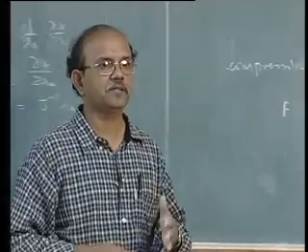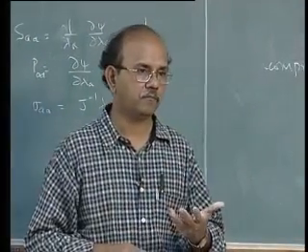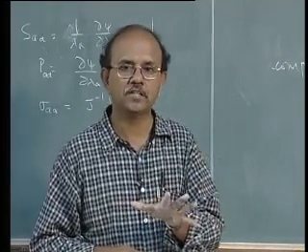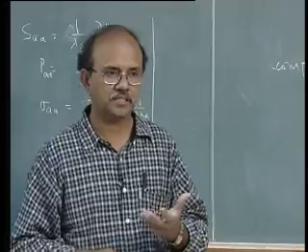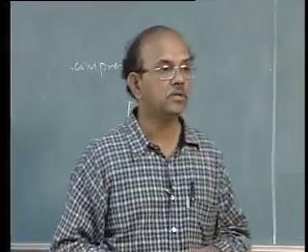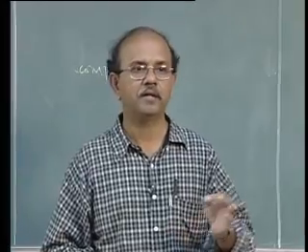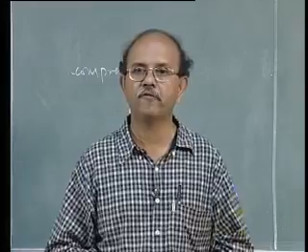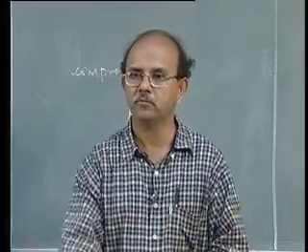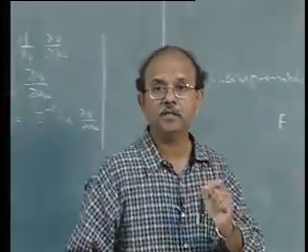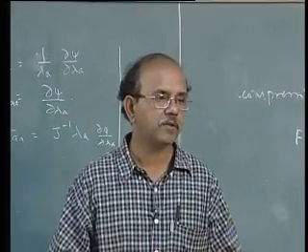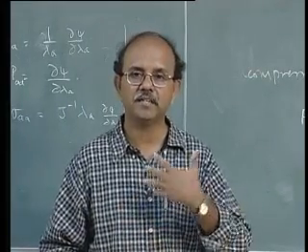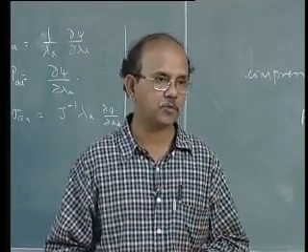Though we say that they are nearly incompressible, in other words, nu in the linear case is 0.499 or 0.495 to 0.499, not equal to 0.5. When nu is equal to 0.5, we say that the material is completely incompressible. But in many formulations and examples, people continue to work with the incompressible case and say that it is incompressible as well.